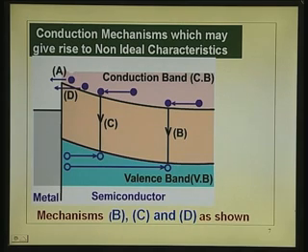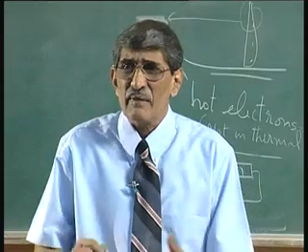Okay. The other current is the generation-recombination current within the depletion layer, recombination in the case of forward bias, generation in reverse bias. There is one more current component, which is the tunneling current. As you go up in this region, the barrier width, for example, if I take it here, it is large. If I go up here, the barrier width is very small. So, once the barrier width is very small, the electrons which are present in that energy can just tunnel through that. That is called quantum mechanical tunneling.